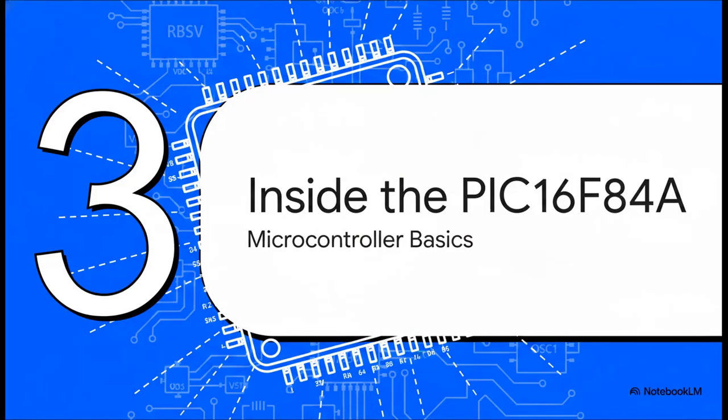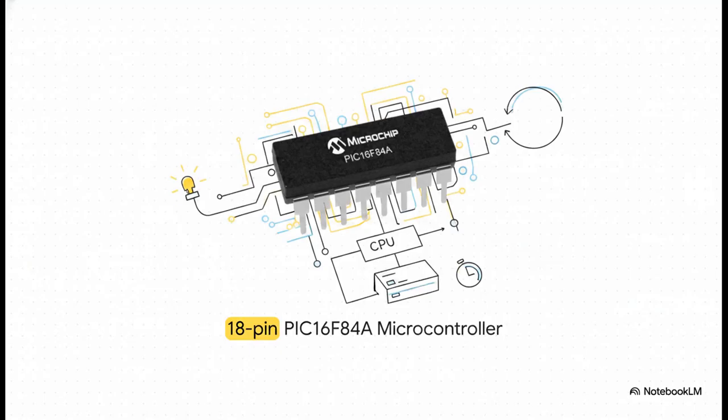Now for Section 3, inside the PIC16F84A. All right, let's step away from this software for a second and meet the actual silicon itself, the physical PIC16F84A chip. This is a foundational 8-bit microcontroller, and honestly, it's the perfect learning tool for embedded engineering. It features a highly streamlined set of just 35 assembly instructions.